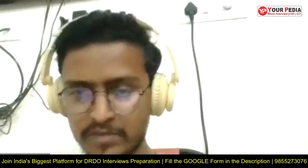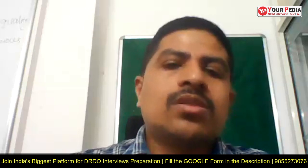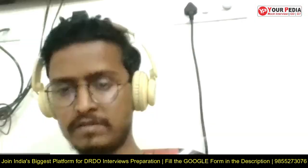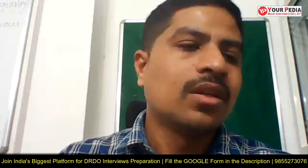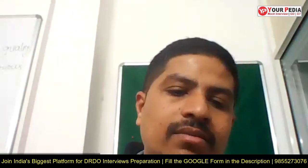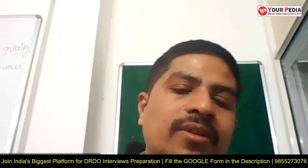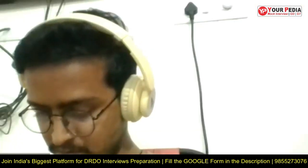I'm calculating the angle of asymptotes. Is it required to calculate? There are three asymptotes, right? Yes. If there are three asymptotes, the angle of asymptotes will be (2q plus 1) into 180 by 3. So 1 into 180 by 3 is 60, 3 into 180 by 3 is 180, 5 into 180 by 3 is 300, that is plus 60, minus 60, 180. Yes, sir. Then you draw the root locus.